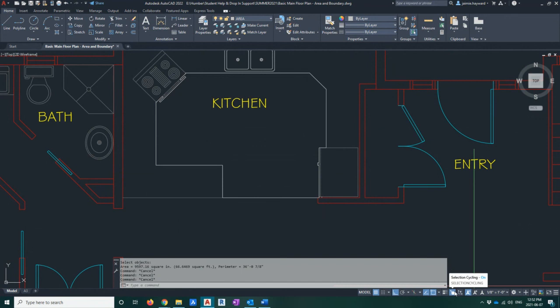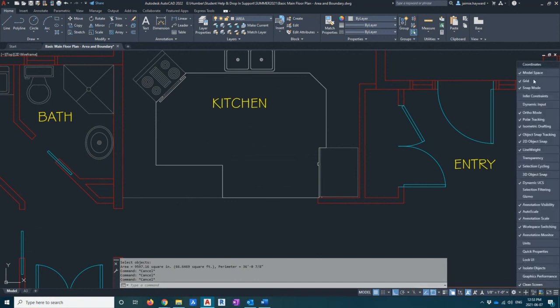That button right there is selection cycling, and let's say all of a sudden you can't even find it down here. Well, that's because maybe you don't even have it shown. So then you're going to want to click on these three lines. These are just what is shown at the bottom, all right? This is not a matter of turning on and off. Okay, I want to be very clear here. These are not a matter of turning these things on and off. These check marks are just a matter of what is shown at the bottom here. Okay, just what buttons is shown, that's it, all right?